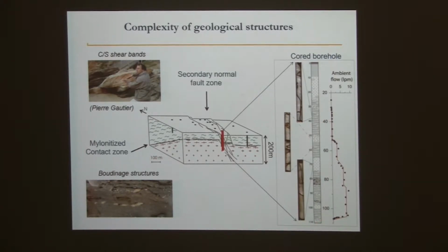And when we look at the ambient flow, which is data that we typically get from a flow meter, what we see is, as Bess mentioned, that in crystalline rocks we would typically have 3 to 4 major inflows or outflows. At each step we typically have some permeability change, but to relate this permeability change to the geology and to know where it comes from is really difficult.